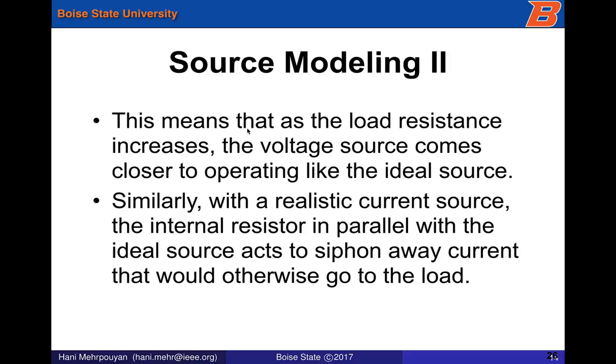Generally speaking, the voltage of batteries actually drops in the cold. So when you go to start your car in the cold, your starter motor uses almost the most power compared to anything else in your car. And when you try to crank the starter motor when it's very cold, the voltage of the battery is already low. But now you're connecting a load to the battery that has a very low internal resistance. That brings the voltage even further down. And so you could run into a scenario where your car will not start. And that's why you need a very good battery to be able to start your car in very cold conditions.